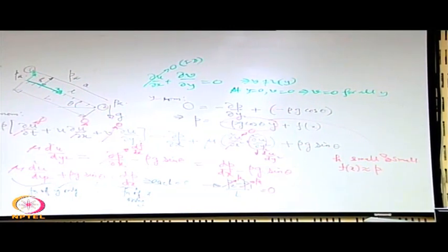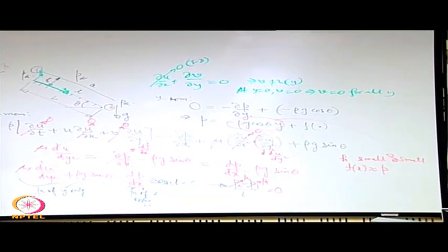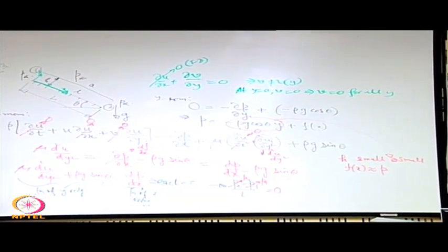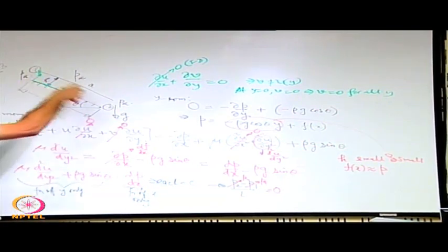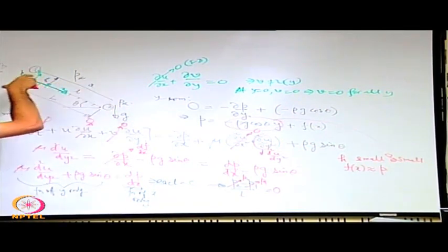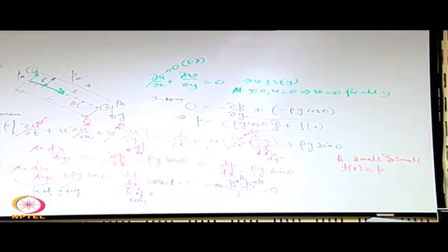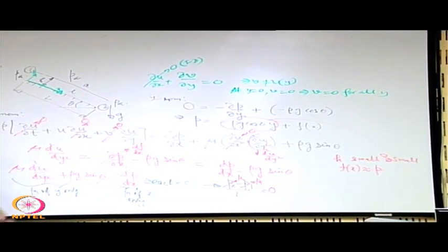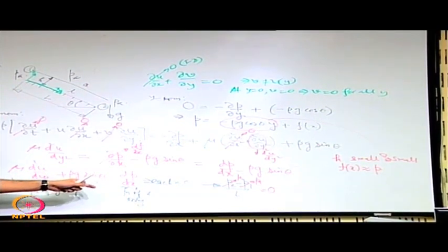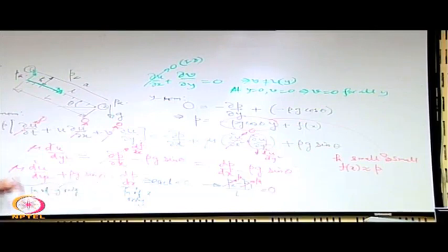We have seen that it's the piezometric head that is important, and the gravity part of the head is giving the piezometric head. So it's from a higher elevation to a lower elevation, and that is what is driving the flow. That is like an equivalent negative dP star/dx. If you include this in the P star, although the P change is not there, the gravity effect is there. And then it is very easy and straightforward to integrate it twice to get the velocity profile.